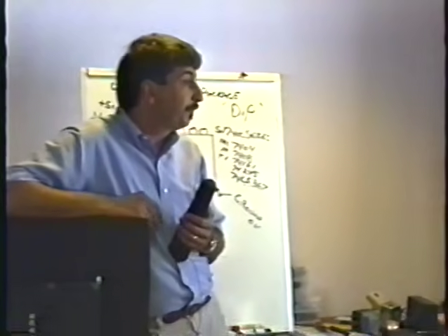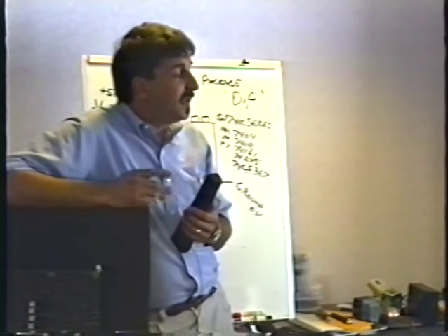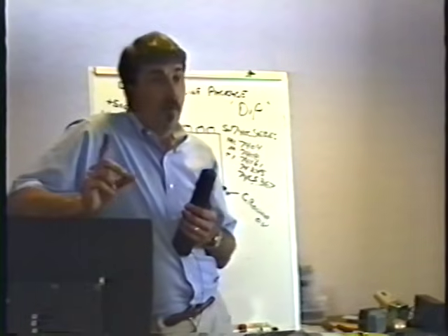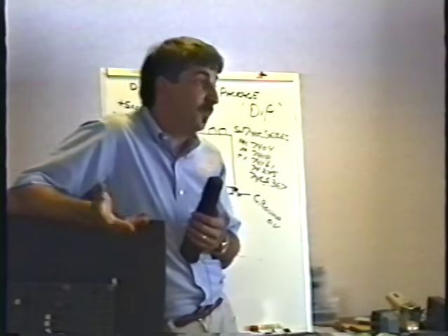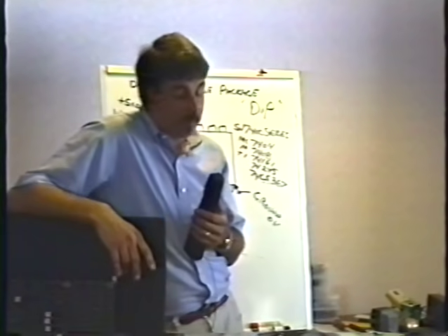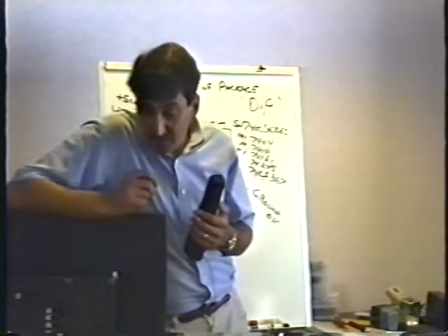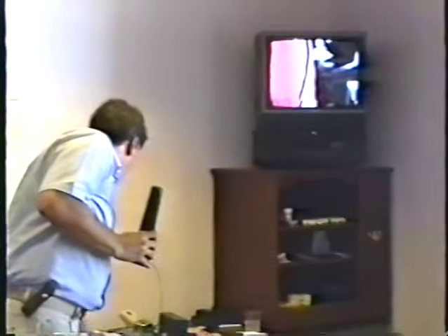Yeah, Susan? What about the opposite? It doesn't work when it's cold. Well, same thing. Same thing will happen. You'll heat it up. It'll be working. When you hit it with the freeze mist, it'll stop working. Same thing, isn't it? Only opposite. So, whatever that means. Okay, so that's another really cool thing that you can do. Any questions about that so far?